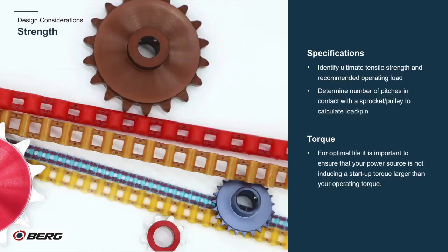The first step in designing a belt drive system is to compute the design power of the system. The required power is based on the speed and torque required to affect the desired outcome from the system. This result is then multiplied by the safety factor to determine the design power. Next, the force in the belt is determined based on the planned sheave and sprocket size. This will be a calculation from the transmitted torque and the pitch diameter. Be sure to follow manufacturer recommendations for belt strength.